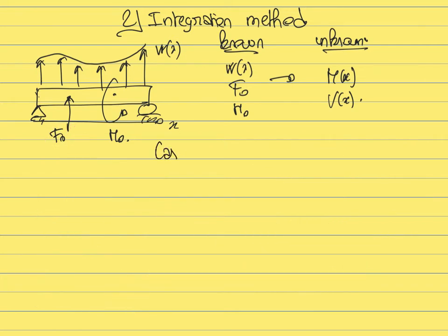And finally, we are going to see case 5, the last case that we are going to see. This time we are going to focus on what happens at the edges. The edges would be the right or the left extremity of the beam, and this is what we will call the limit conditions. The limit conditions are the values of the internal shear and the internal moment at the two extremities, the right extremity and the left extremity of the beam.